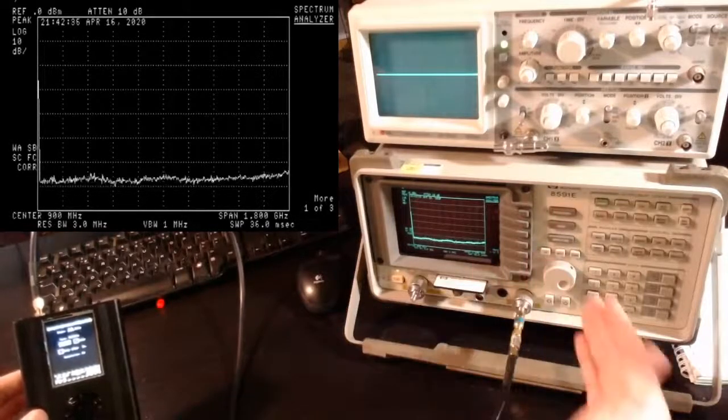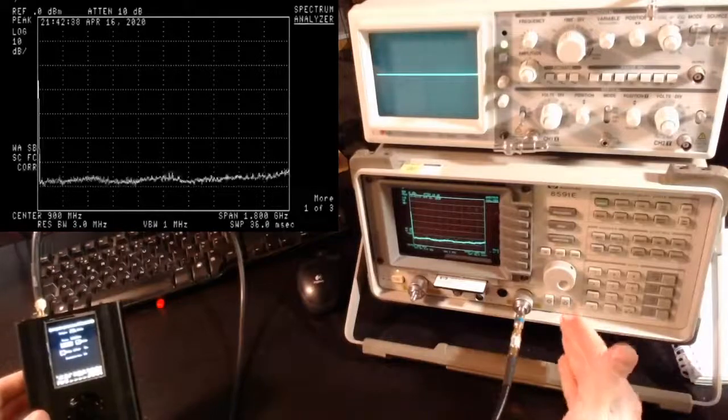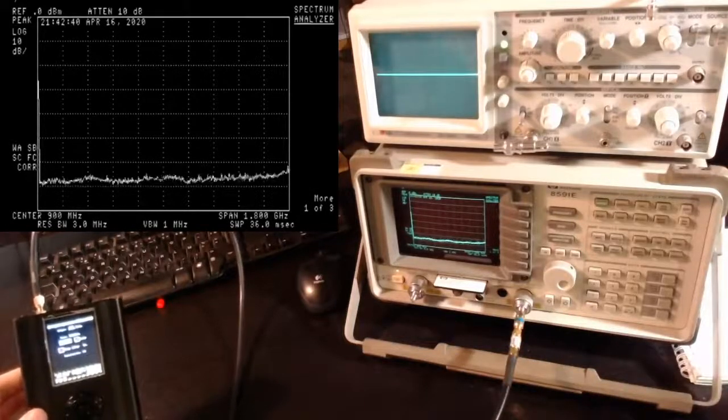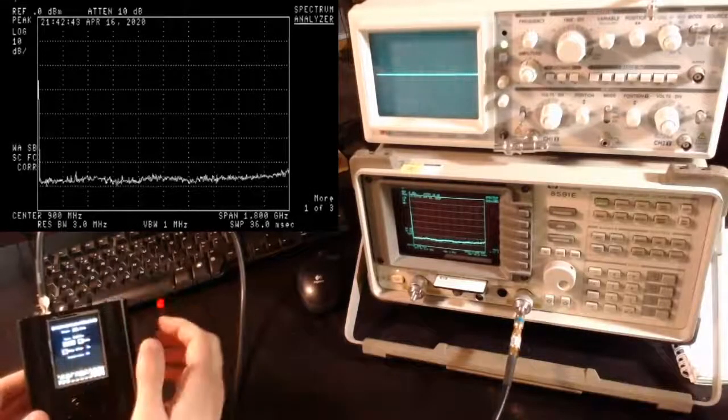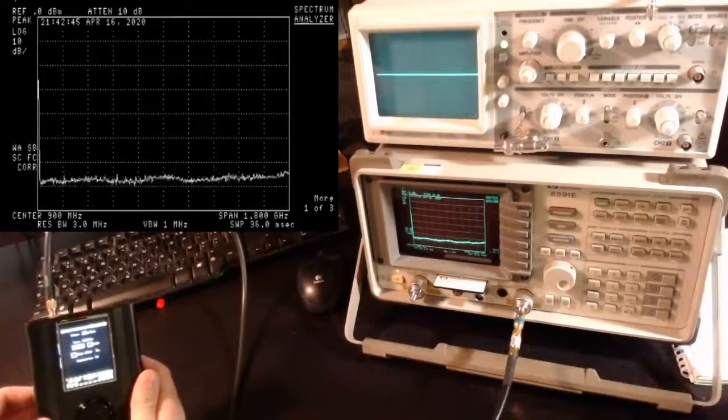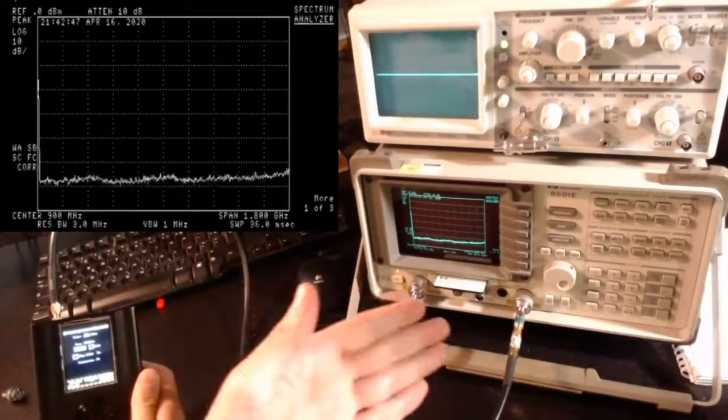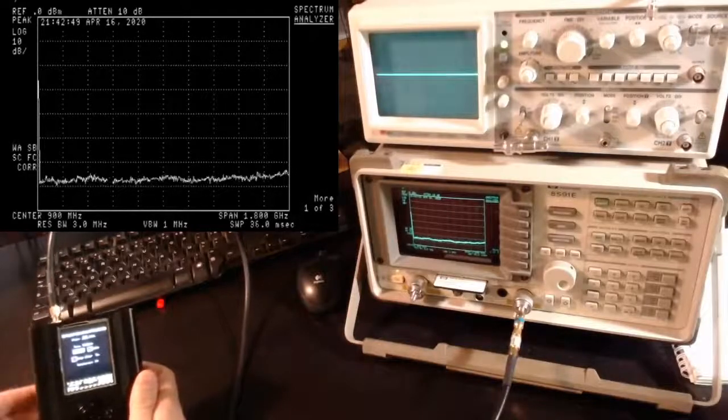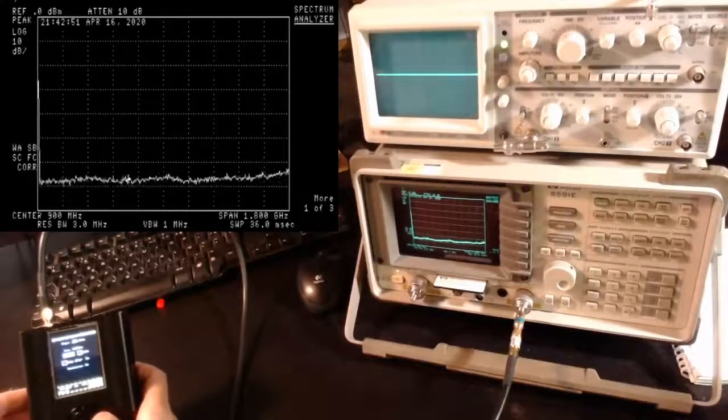It's always good practice to put in a DC blocker and some kind of attenuator, especially with this type of prototypes from China. Really, it's not something you should trust too much with some expensive equipment like a spectrum analyzer. Anyway, enough about that. So we click start,